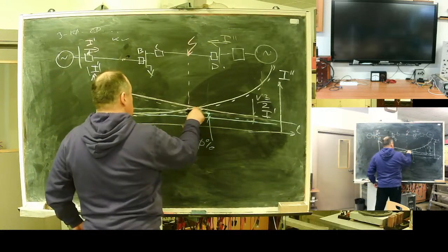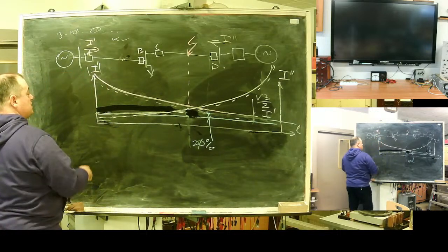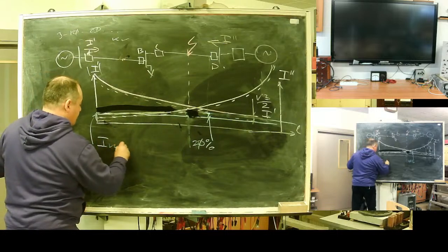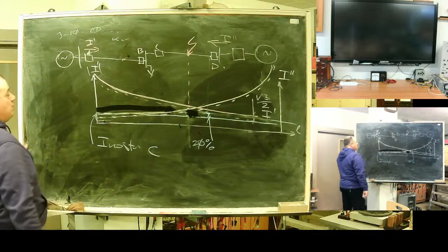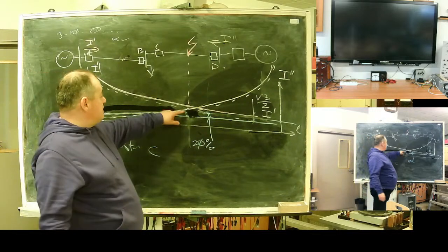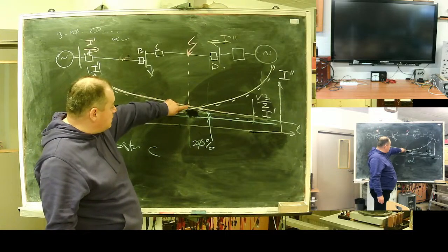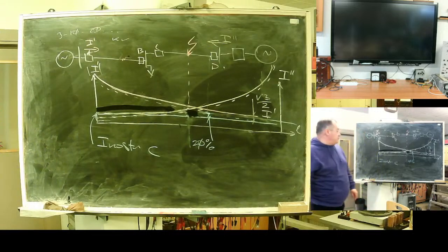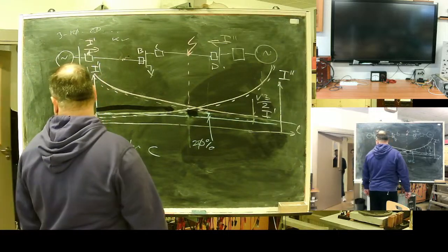Okay, what do we see? The blue line is the trip current, the trip current for the C relay. My relay is sensitive. We can compare. So the fault current is above the trip current, so my relay will be sensitive. In case of this fault, a signal will be sent and the fault cleared.